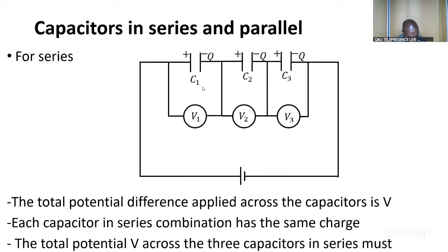Since you have gotten the equivalent, you can now find the charge on each. Don't forget we said that once they are in series, the charges are the same.